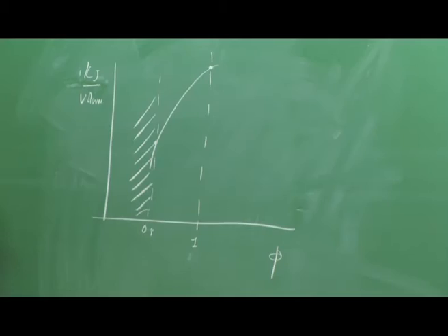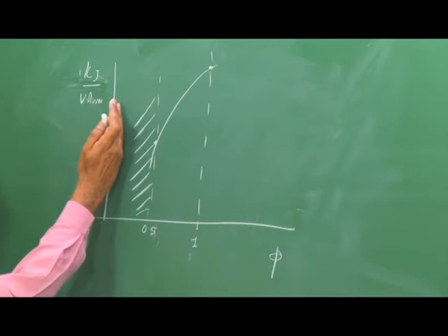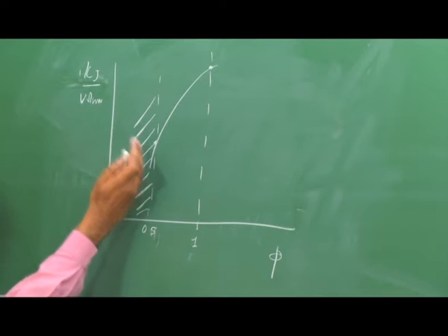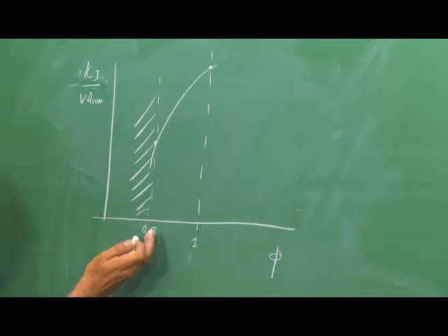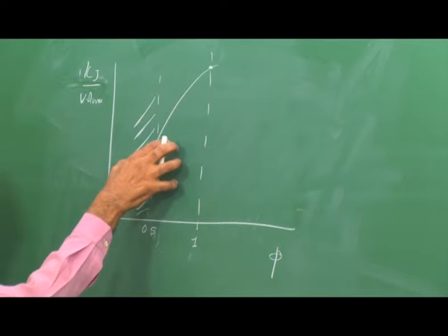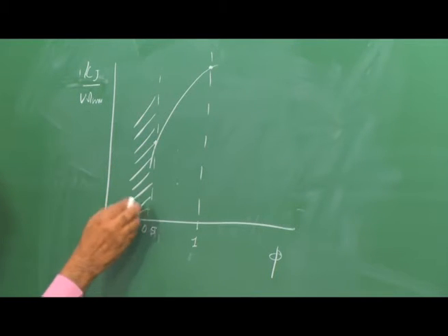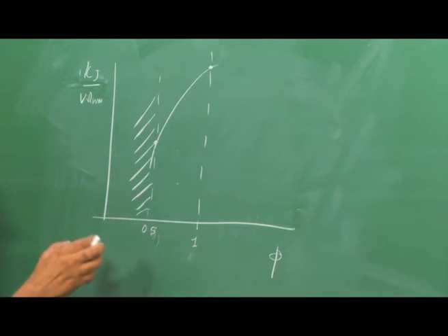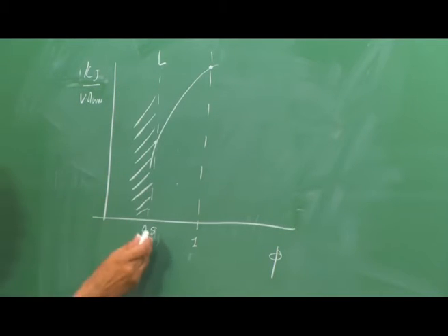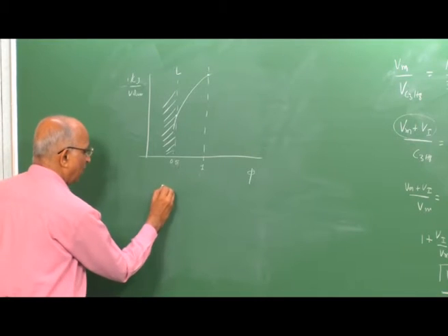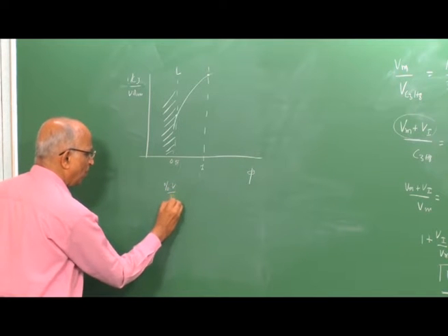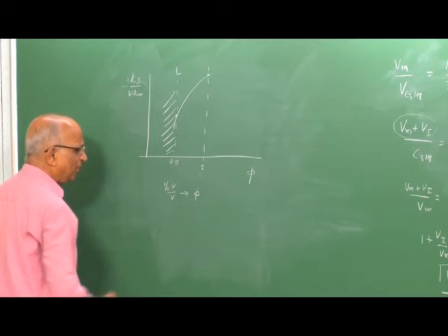The point to be understood is that we are not really looking at very lean mixtures. Even a lean mixture whose equivalence ratio is around 0.5, in the fuel lean region, or below that, just cannot burn; the lean limit corresponds to a value around 0.48. Well, this is how we convert the lean limit from percentage volume by volume into an equivalence ratio.